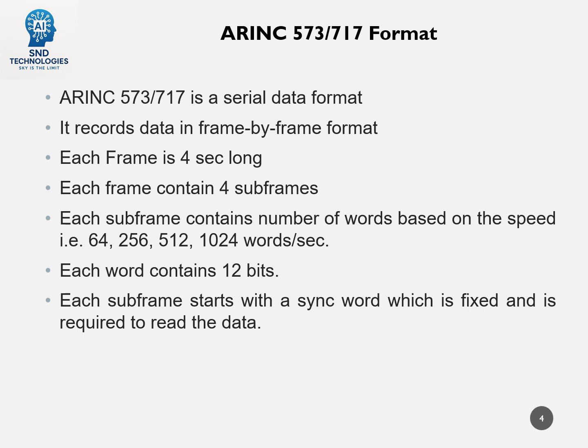And later on, it will just read the rest of the words, and if it is 256 words, it will read the 255 words, and then the second subframe starts, and the first word of that subframe will be a sync word, which will be different from the subframe one sync word, and so on. So it is actually an aid for the listening side to recreate the information which is coming from the sender side.